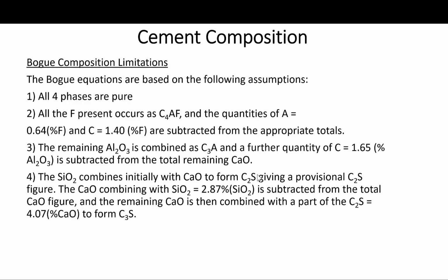A lot of limitations and caveats, but as I said, nonetheless, the equations are an excellent approximation of the phase or compound composition of the cement, and you always have the option to go to the XRD or the reflected light microscopy for additional or added confirmation of the cement composition.